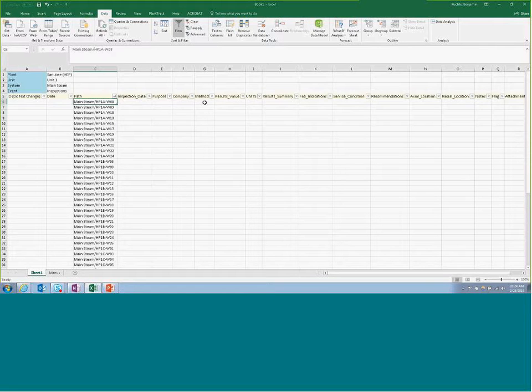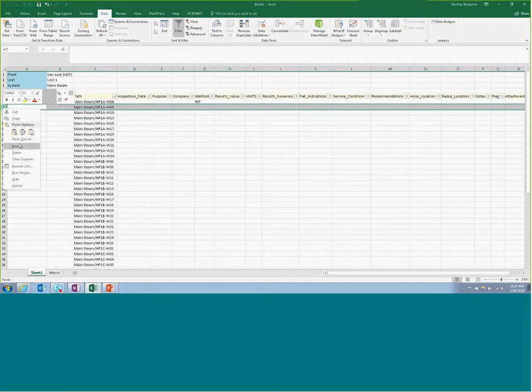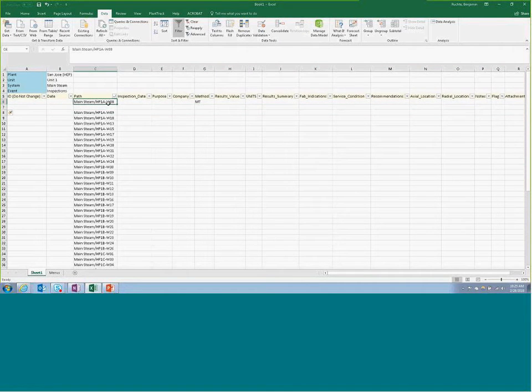So one of the things I can do here is say, all right, for that particular weld, I'll do mag particle inspection, and I'll create another little record, and I want to do LPA, which is linear phased array, and so forth. So I can start to build. I can delete welds I don't care about. I can start to just build an overall scope of work.